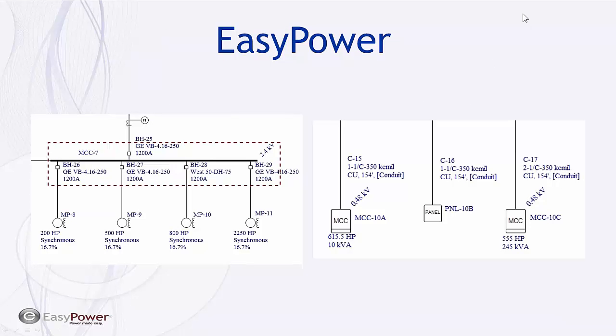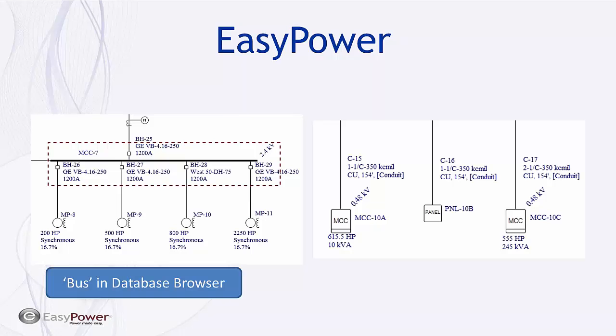In EasyPower, there are basically two ways to deal with this. One is what I consider the individual bus, where we draw out the MCC as a specific bus in the one-line, and then we detail the loads from that, and yet we still consider the whole combination as an MCC device or unit. Secondarily, there's an MCC icon that lets us consolidate all this information inside one element in the one-line. There are trade-offs involved, and that's basically where I'm focusing the next 30 or 40 minutes.